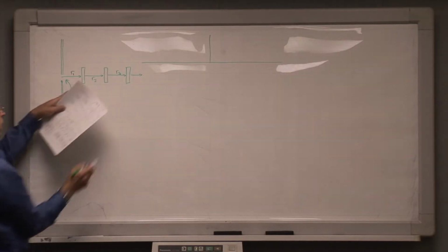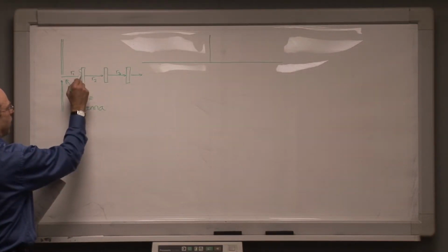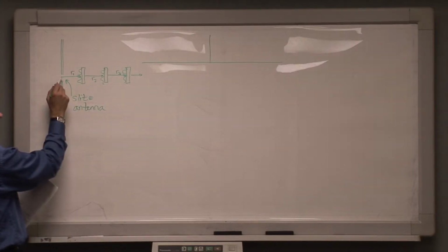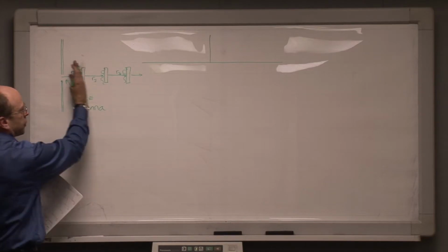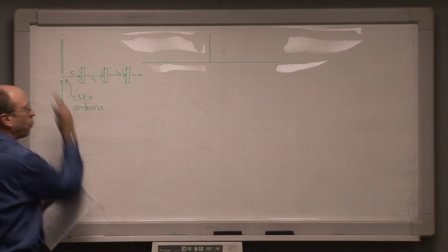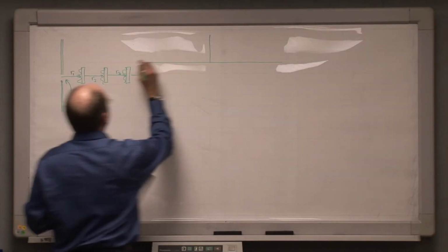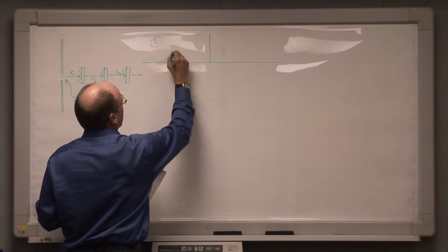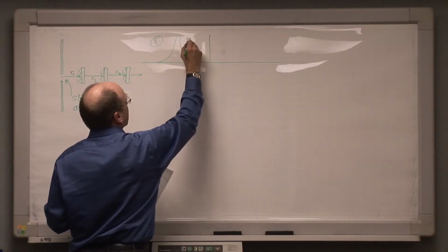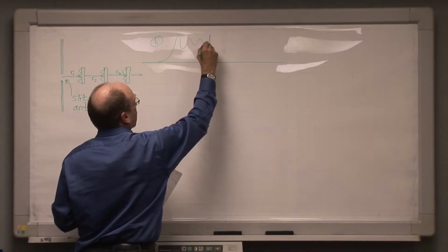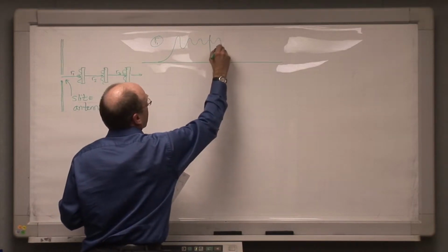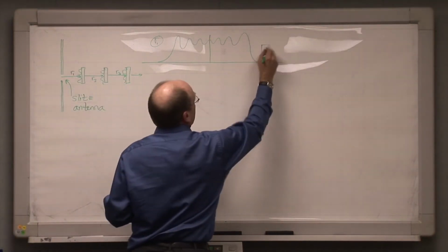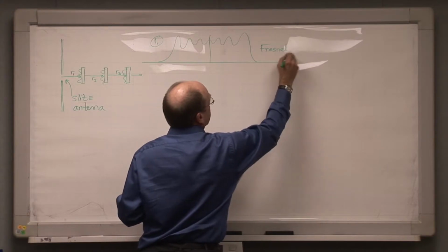And we're going to plot the diffraction pattern as we start out close to our antenna, and then as we move our projection screen further and further away from the antenna. When we're at a distance R1, we will see a diffraction pattern which looks somewhat like this. And this pattern is described mathematically by Fresnel equations.